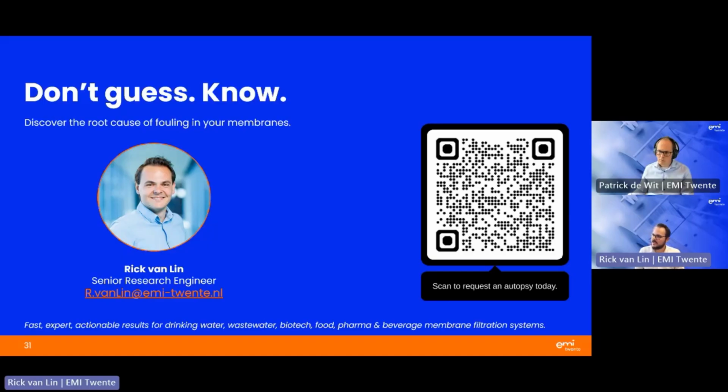So if there's serious inorganic scaling, and then there's some of this slime forming on top, it's pretty safe to assume that this scaling was there before the organics deposited on top. But that requires very delicate handling and looking at the membrane, because if you're scraping it off the membrane layer, then yeah, you're not sure where it was.